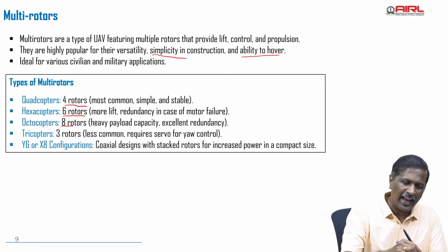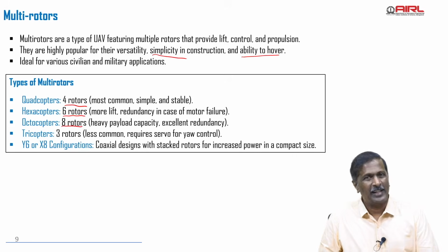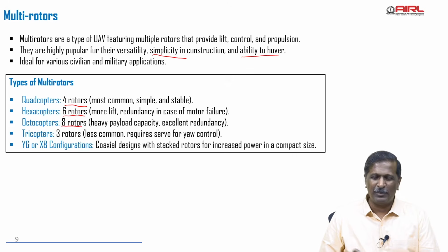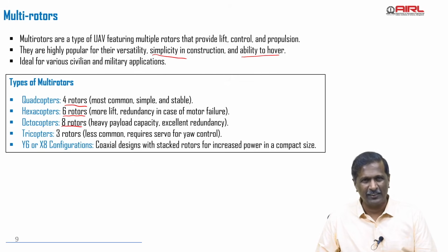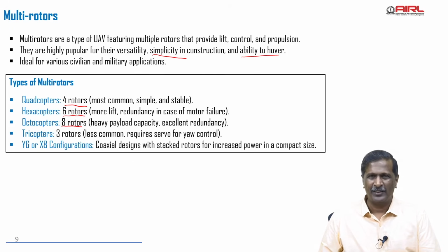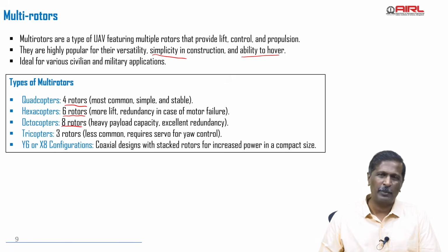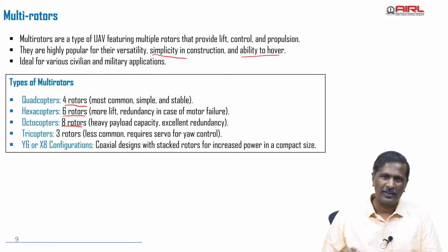Then 8 rotors is highly reliable. Reliability comes with a cost. Highly reliable, less maneuverable, right? So you need to understand that size will increase. You can increase the payload capacity, but then you have to compromise on maneuverability.